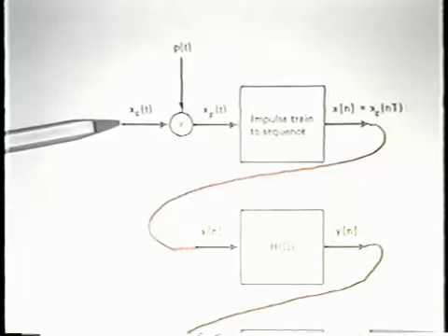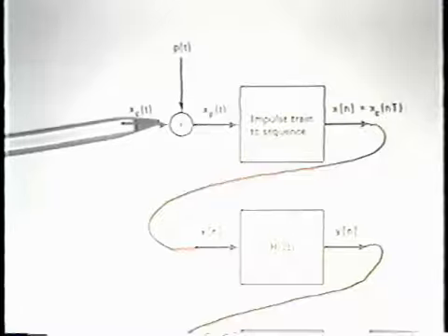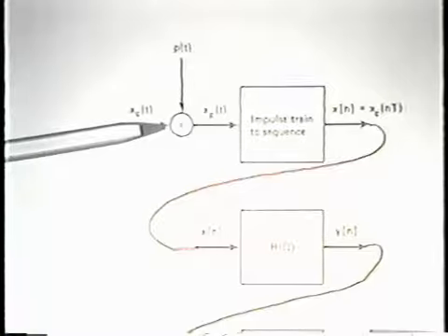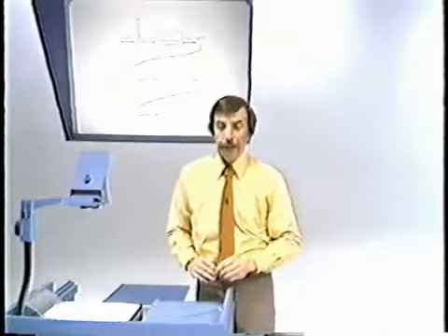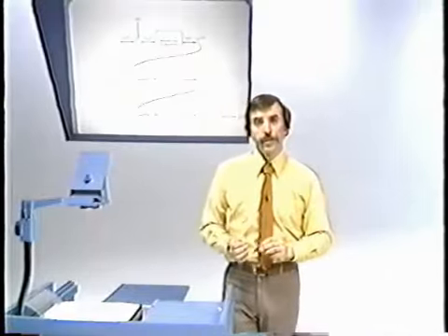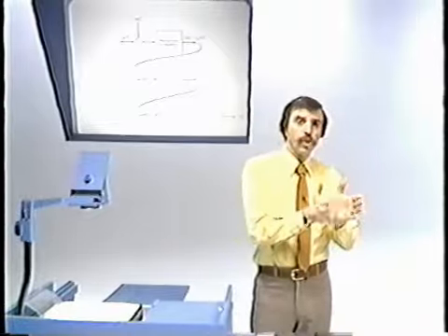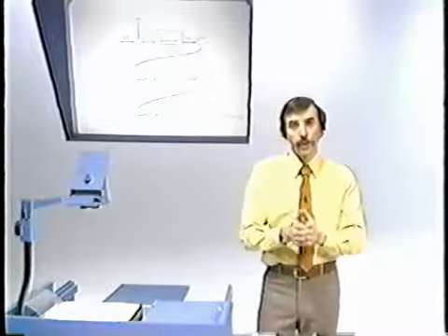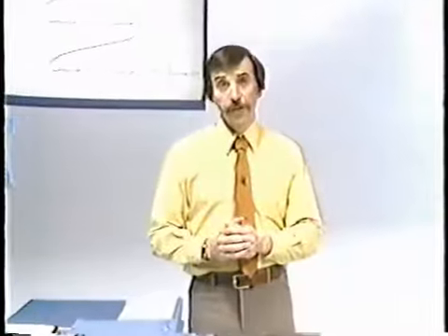It's only, of course, band limited appropriately if we choose the sinusoidal frequency that way. So there is no anti-aliasing filter, and this is the system. And one consequence of that is that, in fact, if we sweep the input sinusoid only up to half the sampling frequency, we'll see no aliasing. But if we let it sweep past that, we're going to get aliasing.